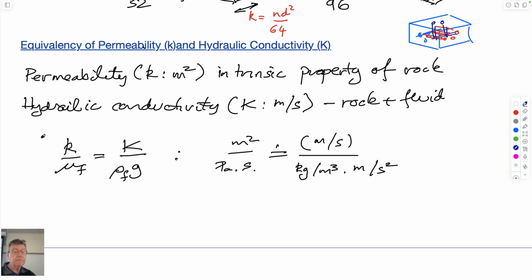And I think the final thing I wanted to say today is, well, we've covered this already, we've used it. This fundamental relationship allows us to link permeabilities to hydraulic conductivities. So the units that are the currency of petroleum engineers and geothermal engineers in permeability versus that of soil scientists and hydrologists, groundwater hydrologists. This is a function of the fluid that's flowing and the temperature you find yourself at. This is a function only of the rock that it's going through.